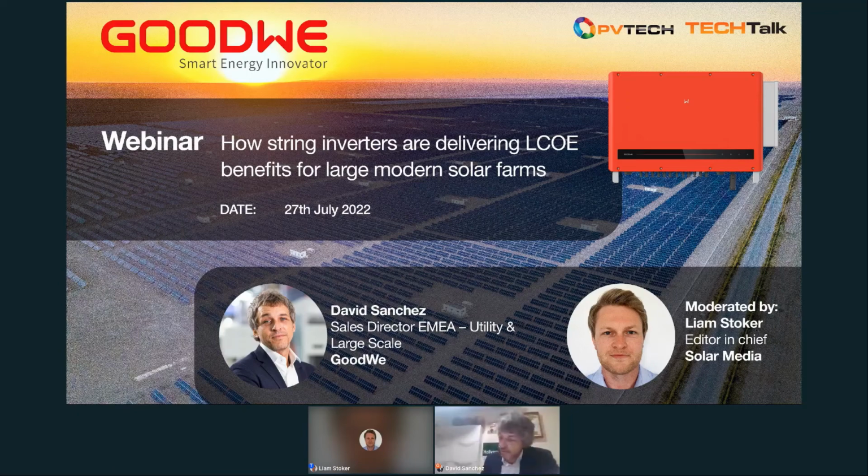Why? Because, as I explained, bifacial modules are already very mainstream, right? And again, this is a rough figure, but I would say that 80–90% of the solar farms globally are already built with bifacial modules. So when discussing bifacial modules and inverters, we need to understand that the bifacial module, though it brings a higher performance, also brings a higher uncertainty when it comes to the rear side generation, right?